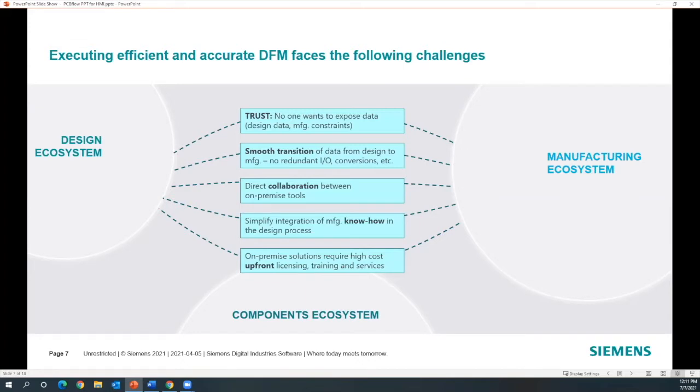Now, also, if I'm making a high density mobile phone, then I'm willing to subject the device to very, very complex processes because I have no choice. But if I'm making some networking board which is going to go on some base station, well, the size is not an issue. I can take more space. So would they use the same constraint file? Probably not. If I'm doing a mil spec design, so also here, I really want to model it and say, okay, manufacturer can tell me, look, I can do high-end manufacturing. This is the cost. Low-end manufacturing, this is the cost. Depending on what you want to achieve, I'll give you the relevant process constraint file. So I think that also has changed.